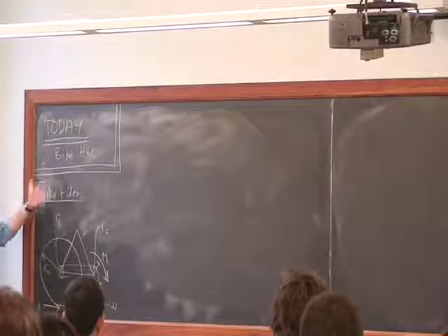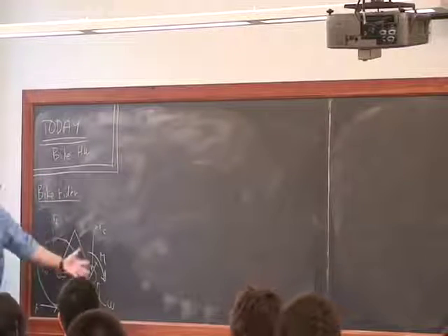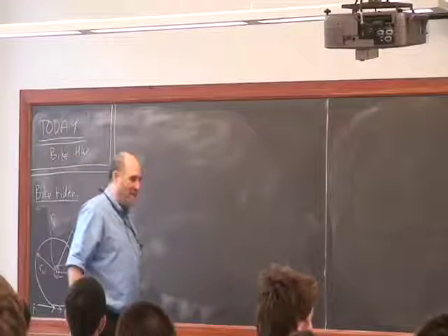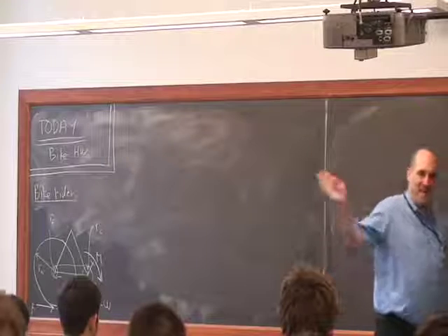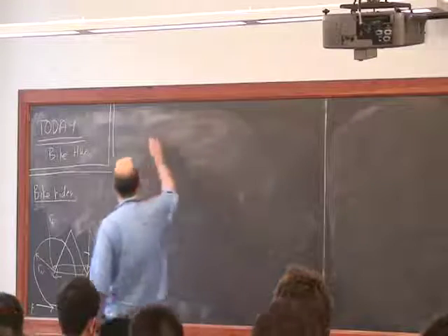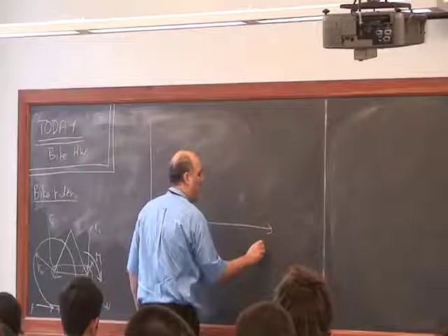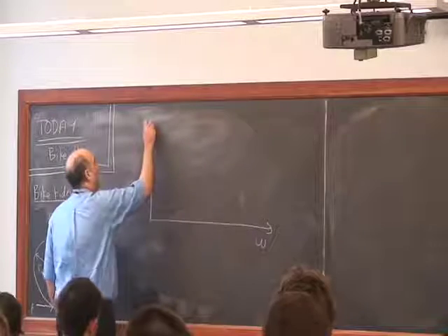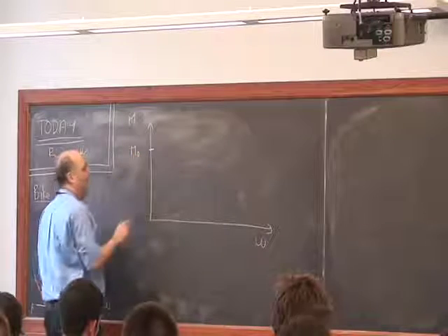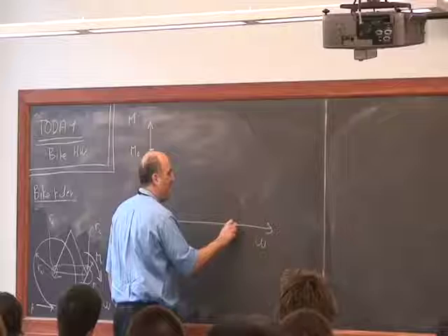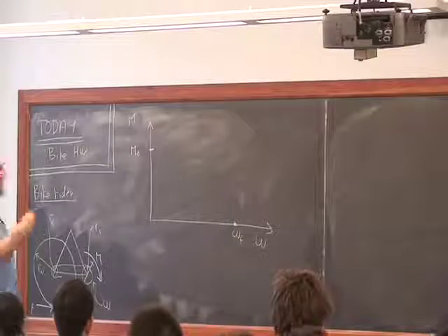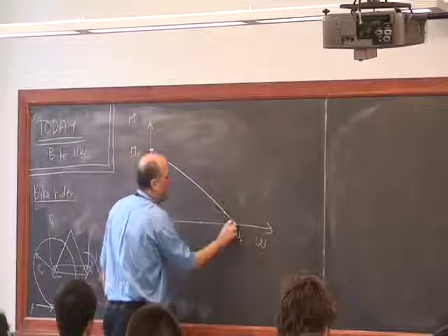So here's how the situation looks. You're on this bike and you pedal, and what you notice when you're riding a bike is that if the bike is stalled, you can push hard on the pedal. And even if there's no load on the pedal, like the bike is going downhill, you can only pedal so fast. You can only keep up if it's going so fast. So this whole concept of this bike rider is assuming you're at your maximum effort. And what you notice is that you can only push so hard on the pedal when it's stalled. On the other hand, if the bike is going really fast, you can barely keep up, and when you're barely keeping up, you're not applying any torque to the pedal crank system. And in between there's something, and we assume it's a straight line.